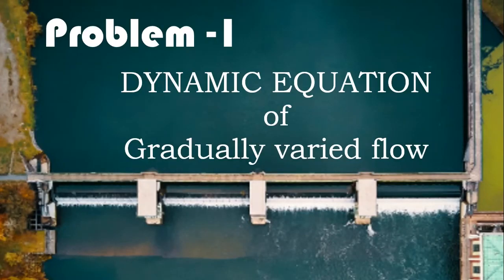Welcome to this video. In this video we are going to discuss problems on the dynamic equation of gradually varied flow. In the previous classes we have gone through the derivation of this dynamic equation, dy/dx equals S naught minus Sf divided by 1 minus Froude number square. So let us use that equation in order to solve these few problems here.